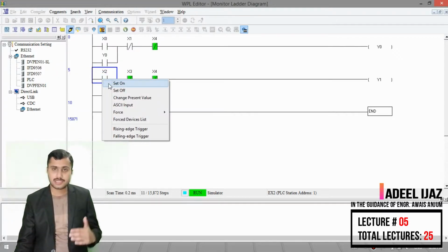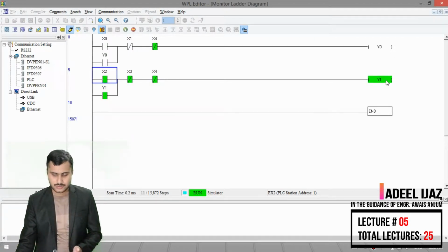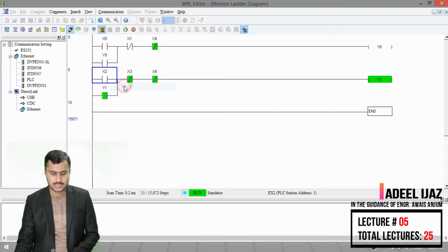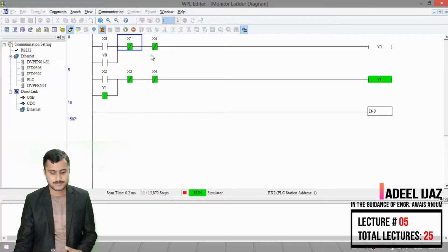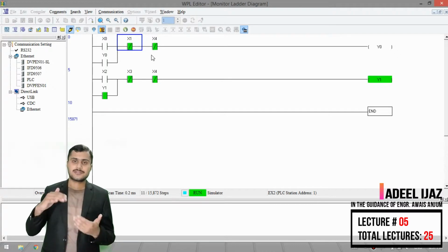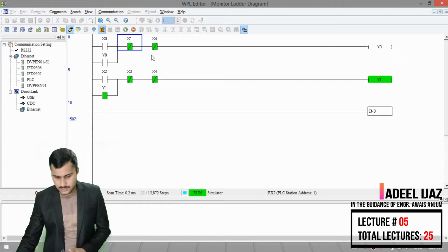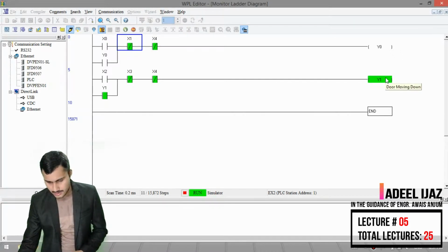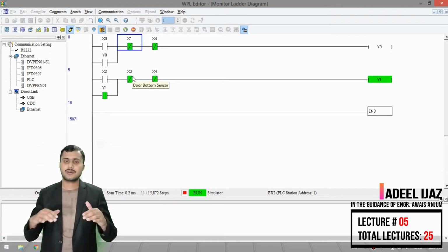So X2 is again a push button, so I press it. Now the door started to move in downward direction and I release X2. At the same time X1 will be disengaged, which means it will go back to its original state because the door is no longer in fully open state. So the door is moving in downward direction, and let's say the door is now completely closed.